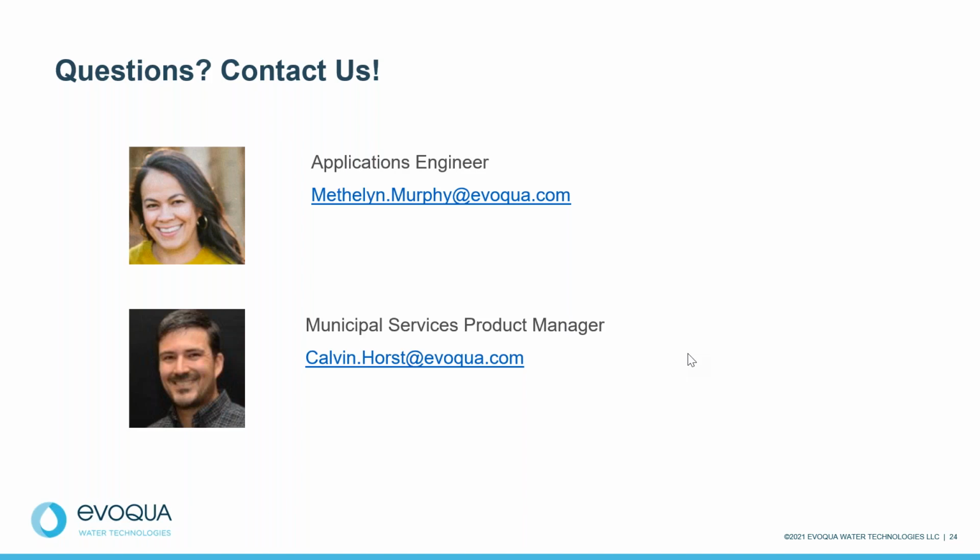Great, thank you. We have a question about special considerations for combined sewers. Okay, so with the application of pH shift products, really we're treating the total flow. So that in most cases would be the total flow of the wastewater to raise the pH at a particular point. In combined sewer applications, of course, we have to worry about runoff and rain events that contribute to that. So it may make it a little more difficult to control.